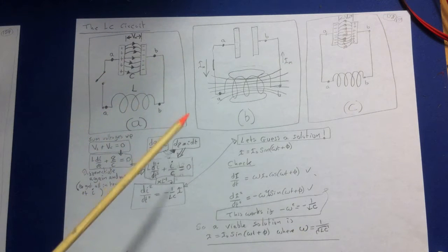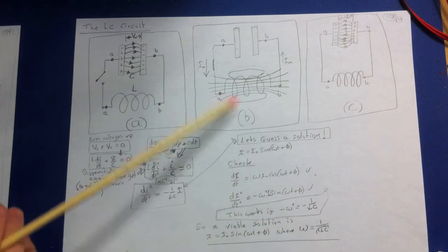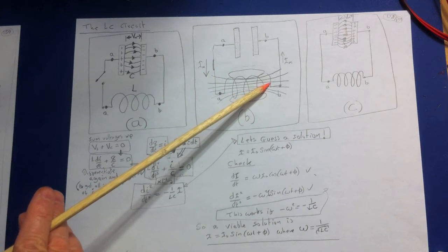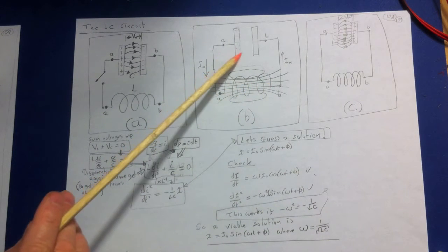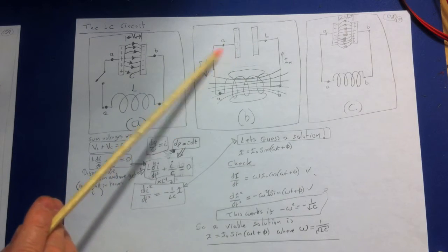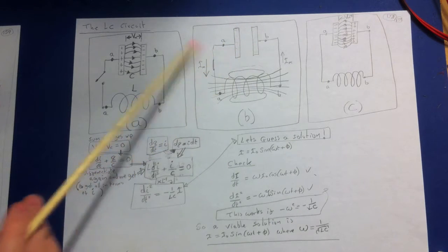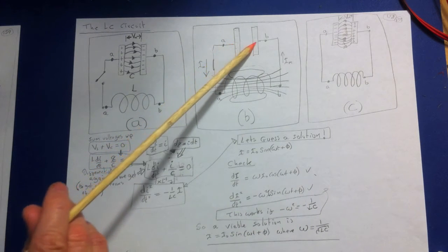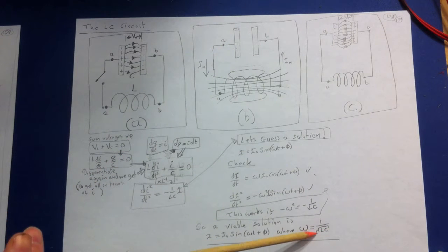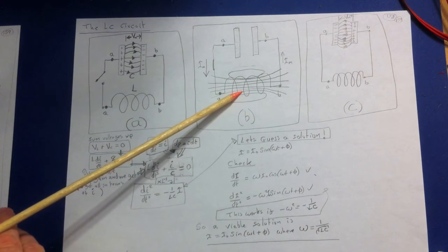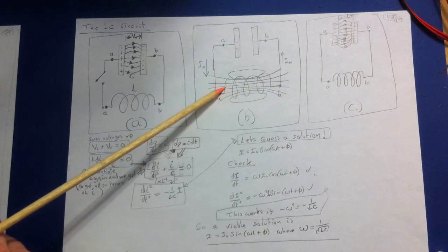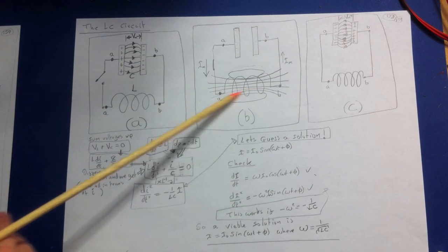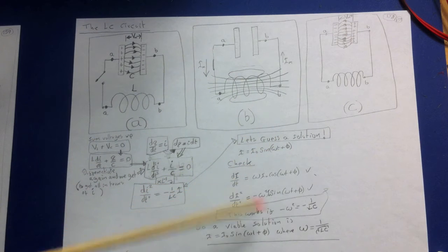You can also reason that out quite easily, because remember that if you've got high inductance, it means there's an opposition, so it takes longer for it to build up the magnetic field. And with C, when C is very large, you've basically got larger plates, so it takes longer for the charges to fill up the plates. And vice versa, if you've got a very small C, then the time it takes to charge up a very small plated capacitor is very quick. And again, a very, very small L means there's very little inductance. The energy gets stored really quickly, and then the current starts to flow much faster, because it only takes a very short time to get over that initial back EMF, if you like. So that all makes sense.